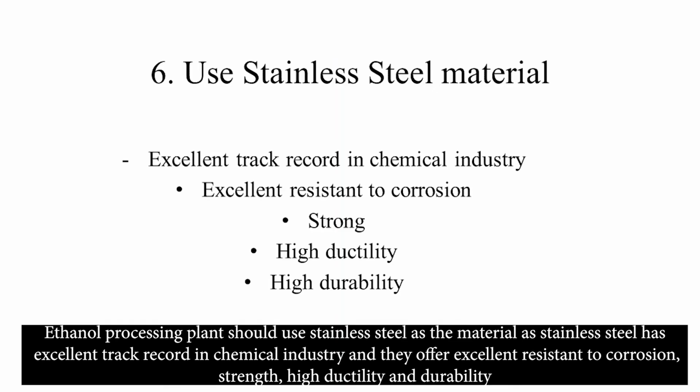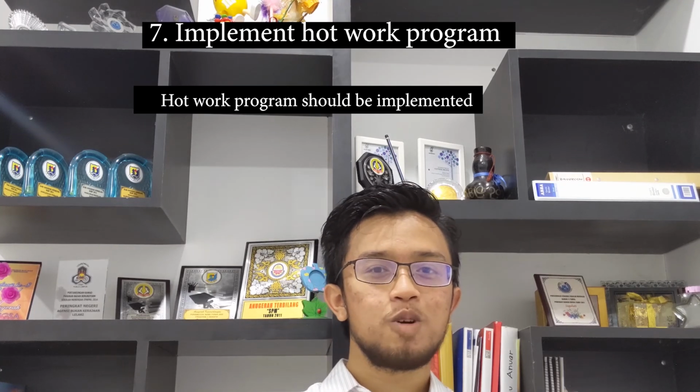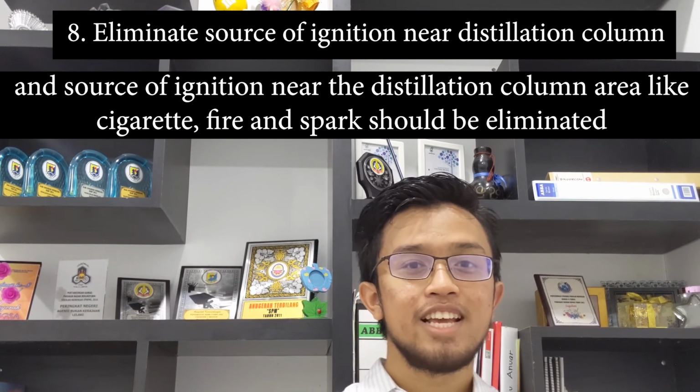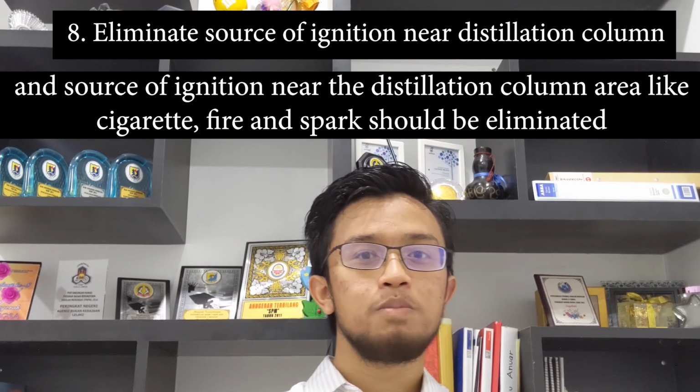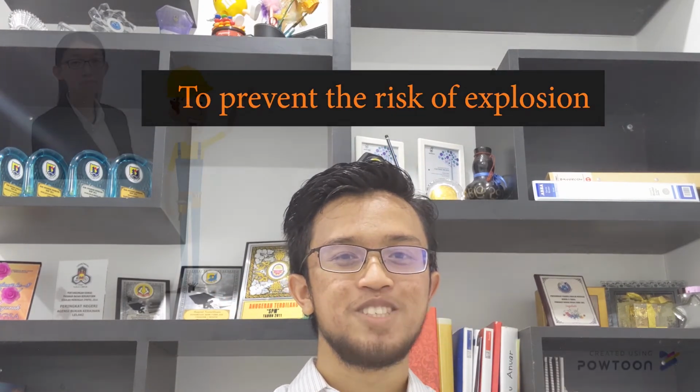The ethanol processing plant should use stainless steel as the material, as stainless steel has an excellent track record in the chemical industry and offers excellent resistance to corrosion, good strength, high ductility and durability. Last but not least, a hot work program should be implemented and sources of ignition near the distillation column area like cigarettes, fire and sparks should be eliminated to prevent the risk of explosion.